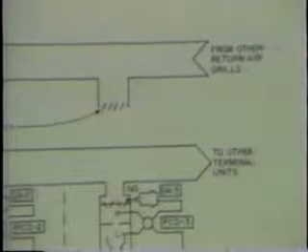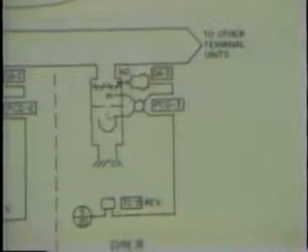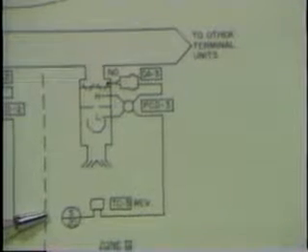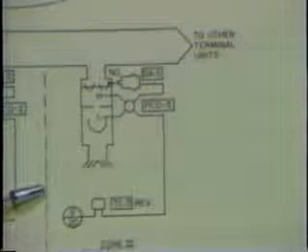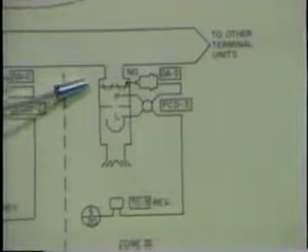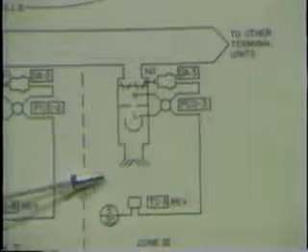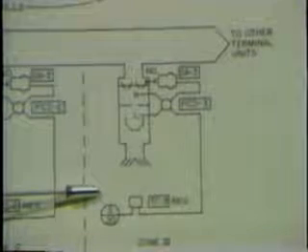1. All-air variable volume systems supply cooling only to spaces. Upon a change in load, the room thermostat's output pressure varies to modulate the terminal unit damper. It should be pointed out that the room thermostat is the master and that it readjusts the submaster flow controller.